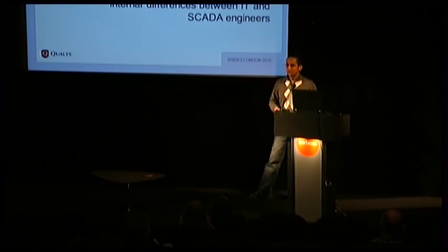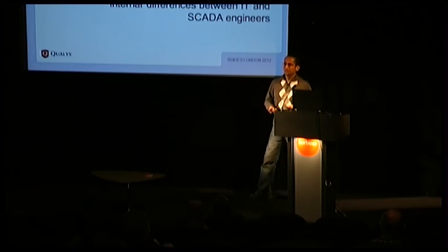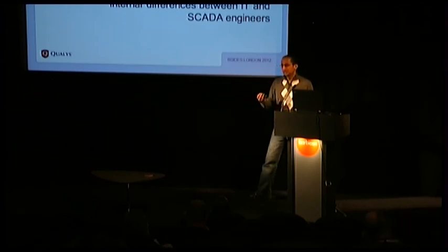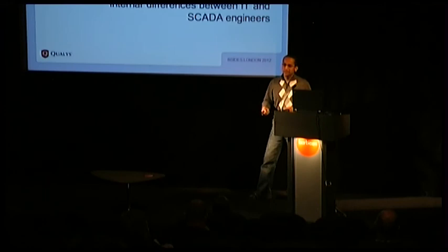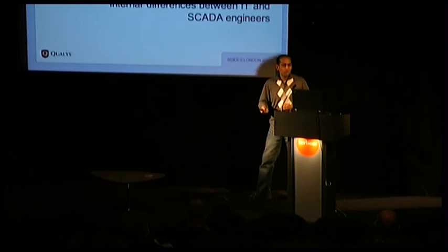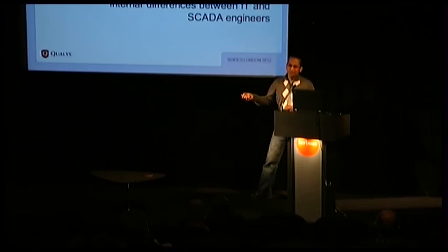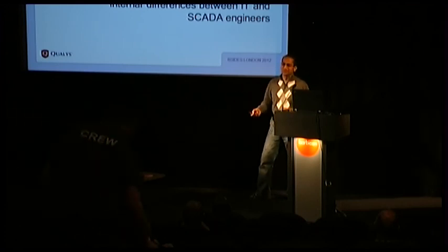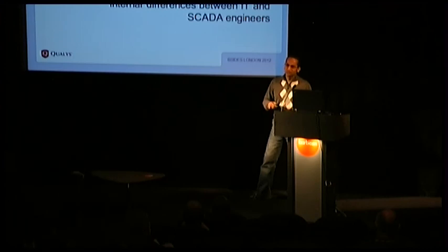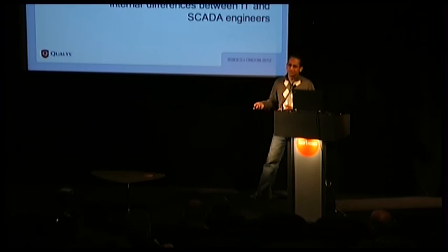These systems are very fragile, they have very little processing power. Many of those PLCs, if they see a packet that they don't know of, if you just ping them, they will fall down because they were not designed to receive unexpected packets as simple as a ping packet. And because of this, the system engineers say, because of your scanning, I had a few hours of downtime on my factory floor. You are never going to scan my system again. And this difference between IT and system engineers basically leads to the system being left unsecured.